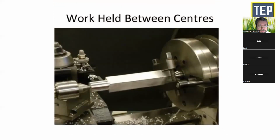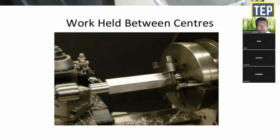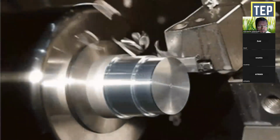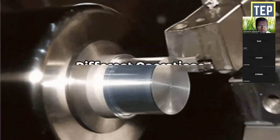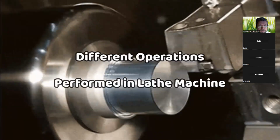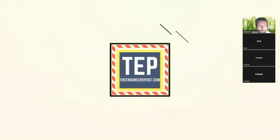The methods of holding the work may be classified under two headings. 1. Workpiece held between centers. 2. Workpiece held by a chuck or any other fixtures. So today, in this video, we'll take a look at the different operations that are performed in a lathe machine.